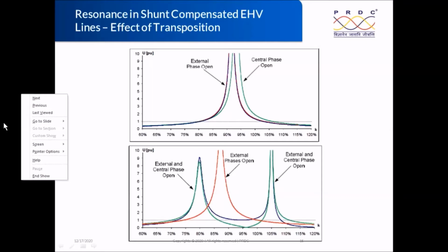And the flows on energized phases are basically based on the power flow. So there is a current flow, and because of this inductive coupling, there is again an induced voltage on the open phase conductor. Some value will be there, but when you compare it with the capacitive coupling, it can be neglected. So it will not have much impact, at least for single circuit lines.